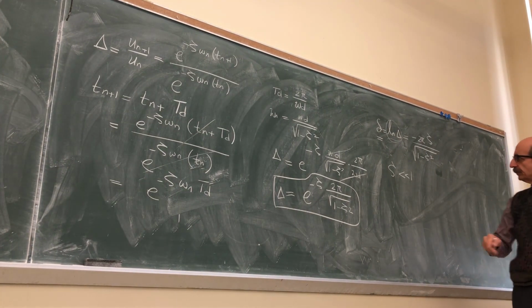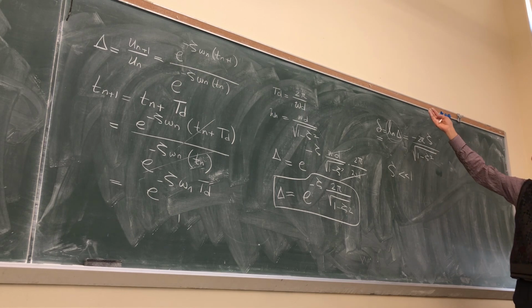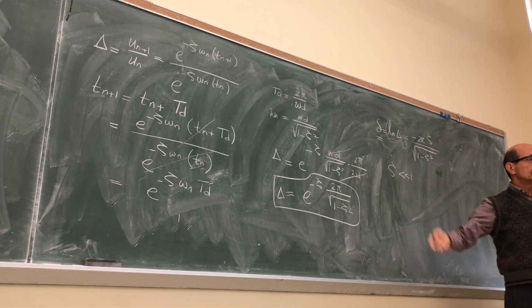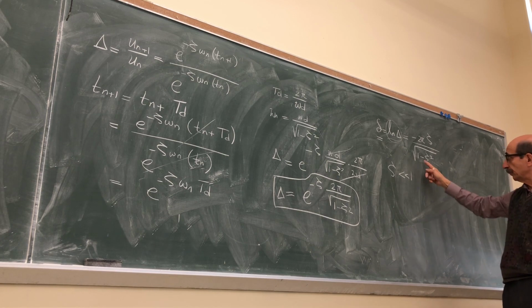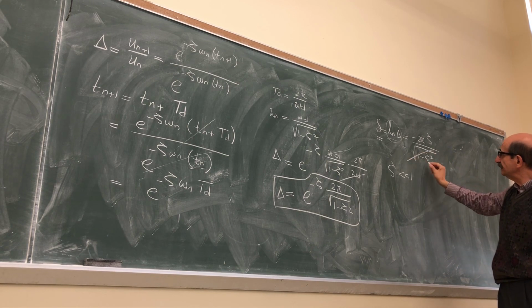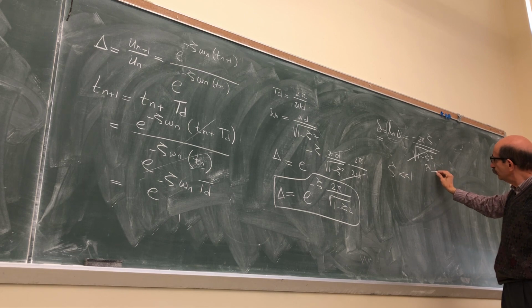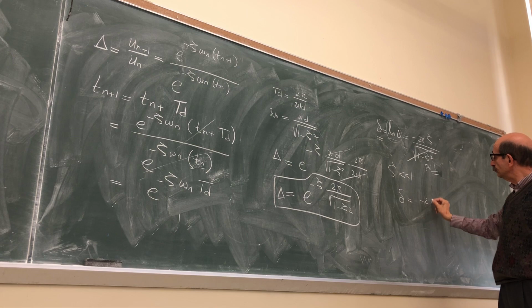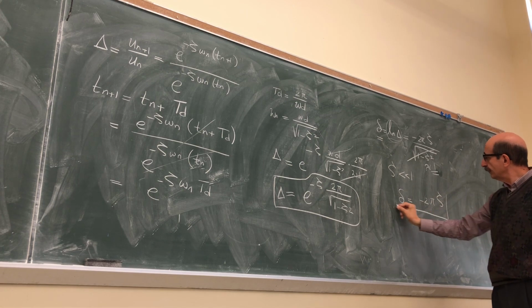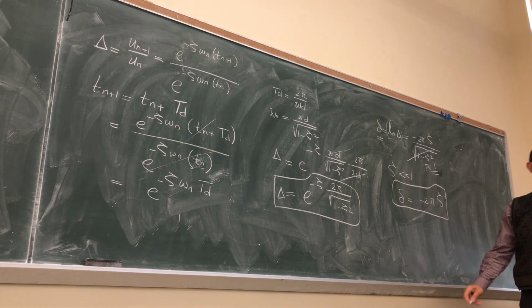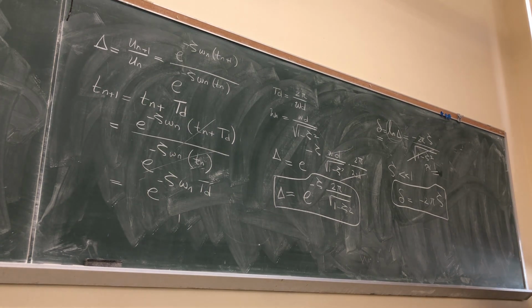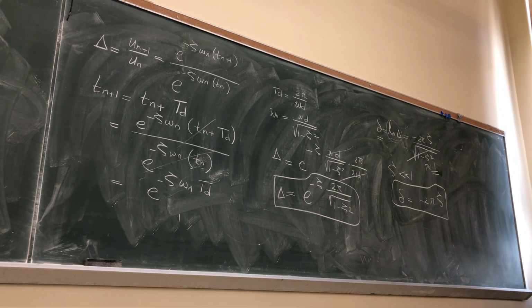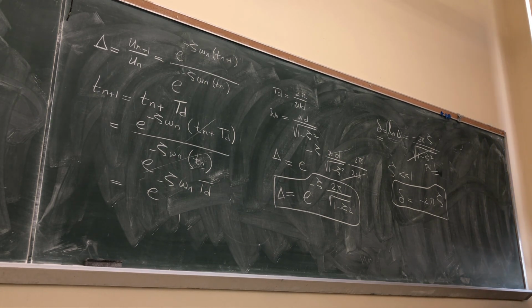So you're talking about, let's say, 0.2 squared, which is what? 0.04. So it's very, very small compared with 1. So you can say this is almost equal to 1. Therefore, delta is actually 2 pi zeta. This is a very easy way to measure the damping ratio in a system, and that's one of the applications of the free vibration of damped systems that you can see.